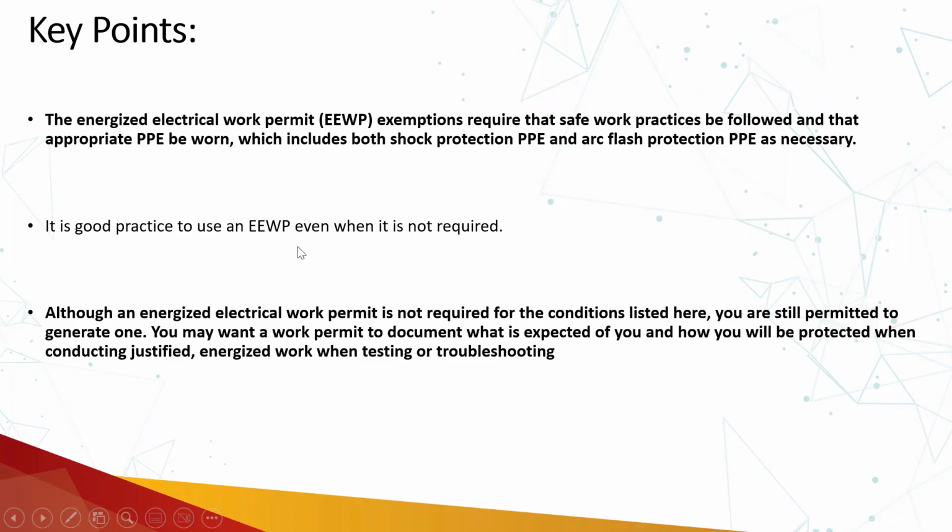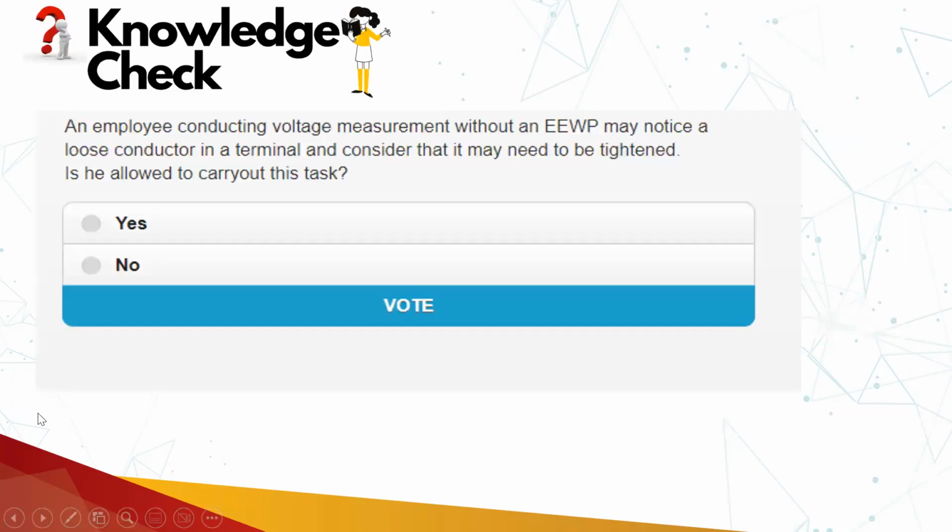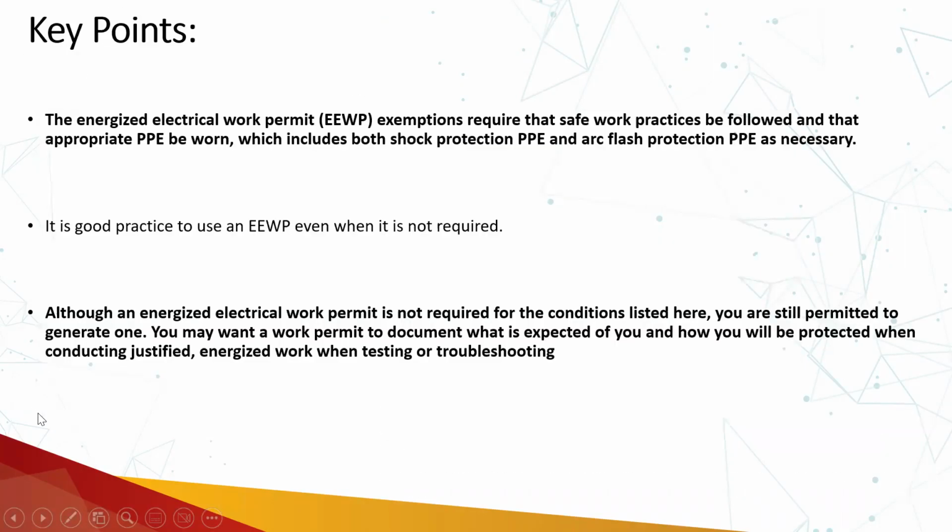It's a good practice to use an energized electrical work permit even when it is not required. Although an energized electrical work permit is not required for the conditions listed here, you are still permitted to generate one. You may want a work permit to document what is expected of you and how you will be protected when conducting justified energized work, when testing or troubleshooting.